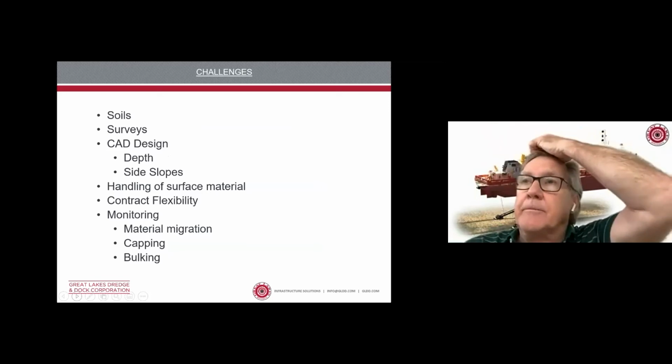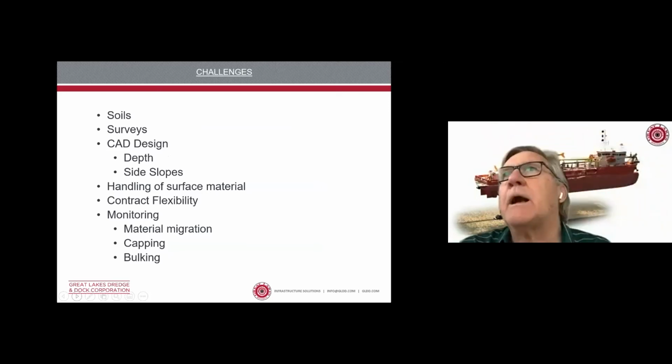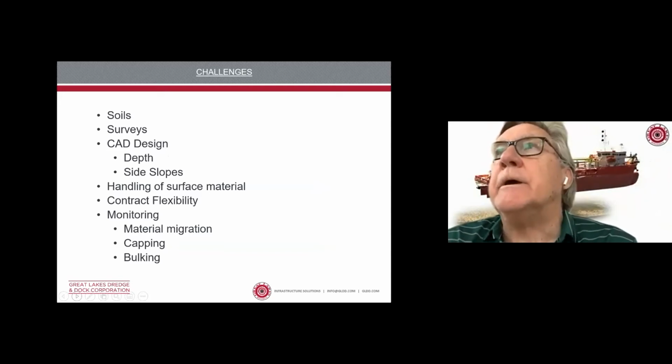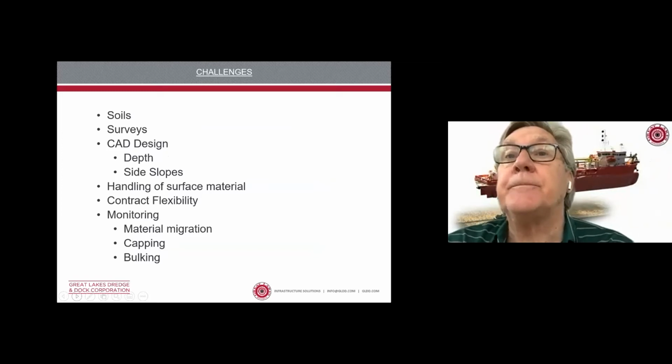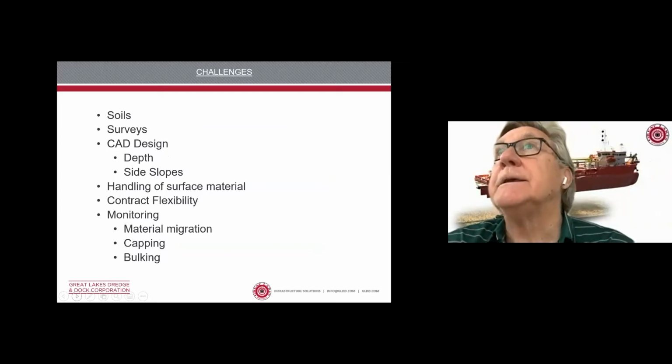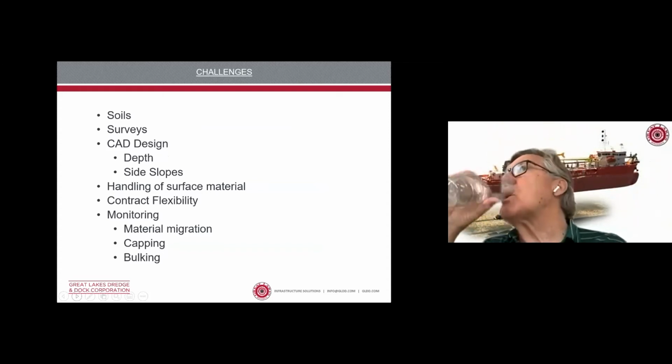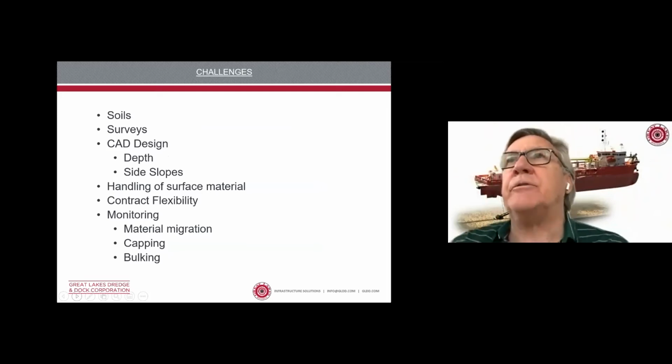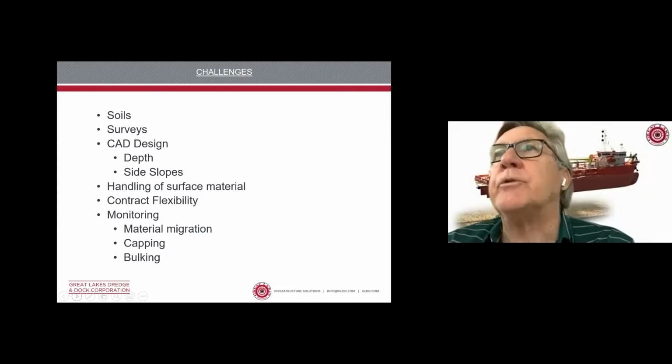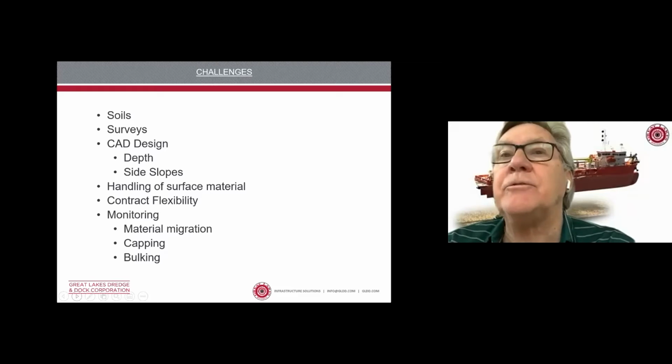Some of the challenges, several of the previous speakers have already talked about soils. I'll repeat this because the top 2 items, if you're designing any dredging project, the 2 most critical things are soils investigations, soils characterizations, and hydrographic surveys. Everything we do in the estimating process to try to understand the project we're bidding on has to do with soils and surveys. So you cannot have too much geotechnical information, and you can't have too many surveys. In this case, removing surface contaminated materials, whether it's to a predetermined elevation, or just to a harder bottom, that information is very important to divulge and be transparent with the contractor.